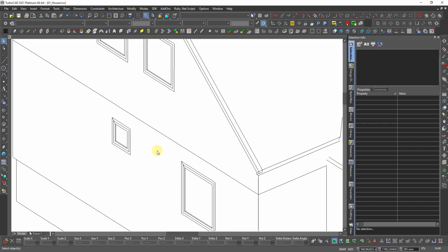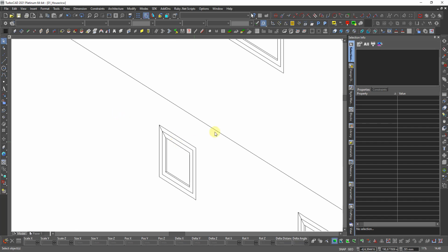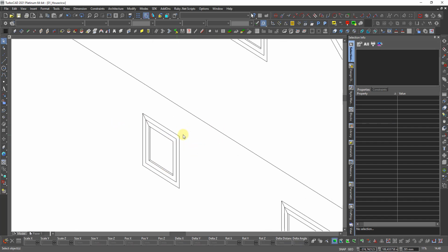If we have a more modern style house with the new technical stuff on it, demand for insulation, this should be minimum 25 millimeter inside the wall, because otherwise there will be a lot of fog, moisture fog on the window, because the difference in temperature will be so big.